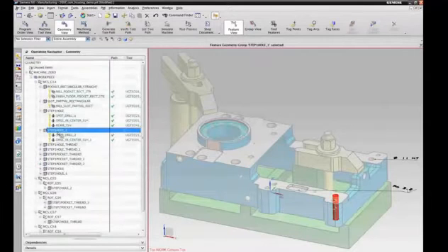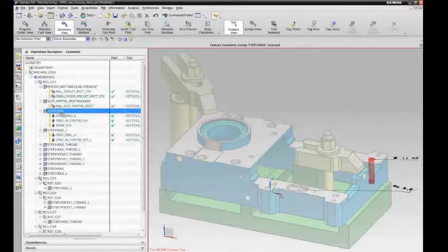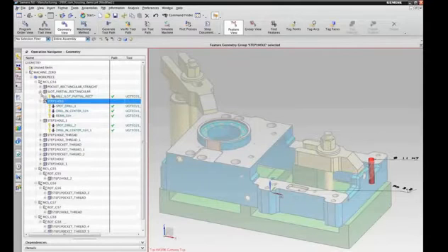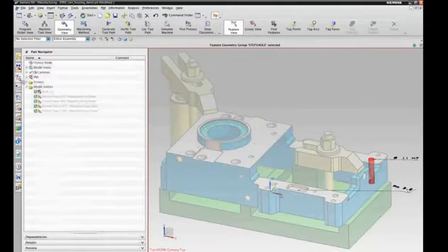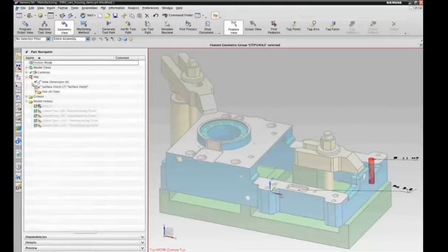The plus minus 0.2, we just spot drill and drill it. The highly toleranced hole requires different operations, and in this case it requires a reaming operation. So feature-based can look at not just the geometry but at the PMI as well. Let me continue and make one change to show you the impact of PMI. So I have PMI defined, and one of the PMIs that I have defined is the surface finish here,